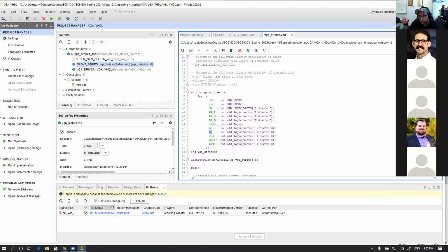Do you remember the HC and HV that I created? The counting? Those will tell me the horizontal and vertical definition of the pixel. So this pixel, this pixel, this pixel, this pixel. So with VC and HC I can start sorting them, so I can make a funny face or whatever I want. Then, of course, the red, green and blue will finally be connected to who? To the XADC, right? That makes sense?